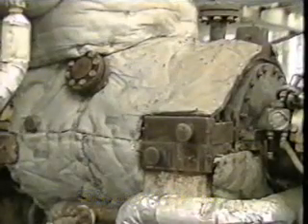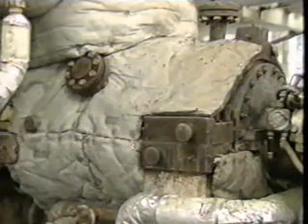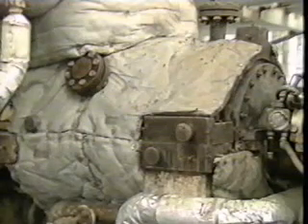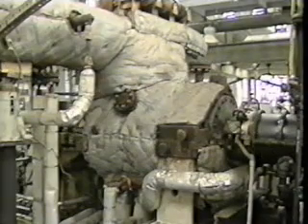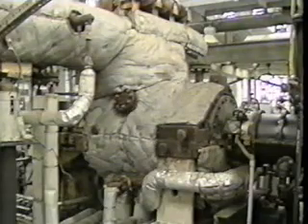Commonly, steam and gas turbines use speed-increasing gears between the turbine and the compressor. Steam and gas turbines generally rotate at high speeds and therefore can sometimes be used to drive high-speed centrifugal compressors without any gearbox. This is known as direct drive.